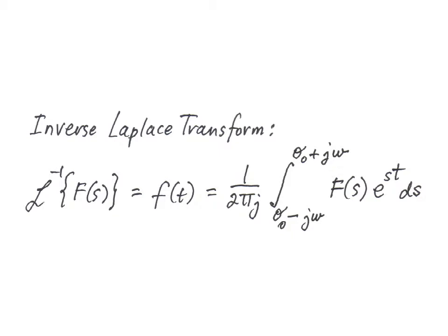Of course, j omega is changed to sigma plus j omega, or s. And the integral, instead of taking place over all omega, it now takes place for all omega when sigma is held constant for a particular value sigma naught.